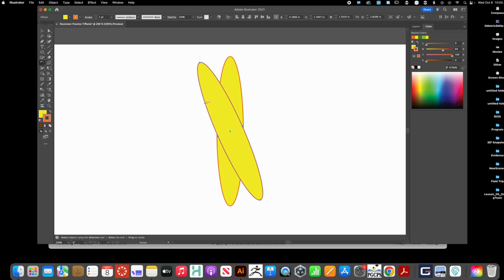From there, the next thing was to use Command D to transform again. So once you click, hold, and drag, you made a copy of the original, but you also did a transformation as far as the position of that particular petal. Illustrator recorded that, so it knows exactly how far you went to the left in degrees. We can go over that later too.